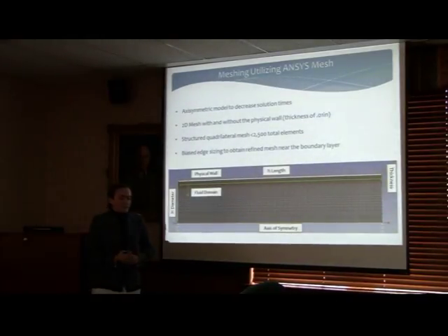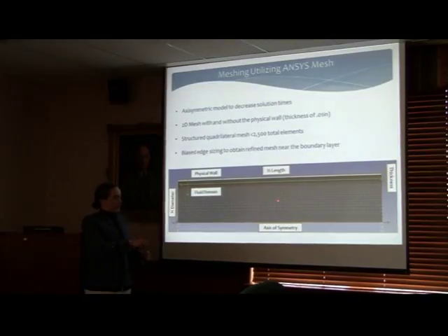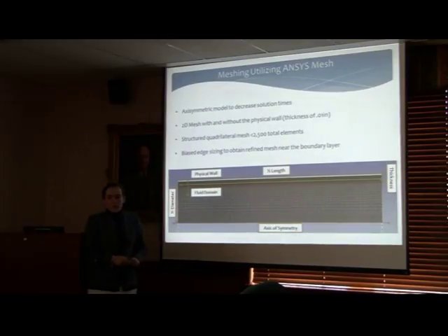So the next step, pre-processing, setting up before Fluent, is meshing. Meshing is when you take a geometry that you've built and you cut it up into a bunch of little tiny pieces, and for each of these tiny pieces, you're going to solve the energy equation, the continuity equation, the x and y velocity equation, so that it all balances out to 0 in one of those little things. For this, the smallest one that we had was about 0.02 inches squared, and that was based off the thermal penetration depth.